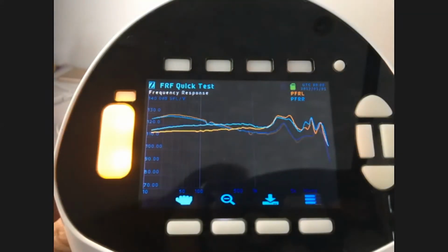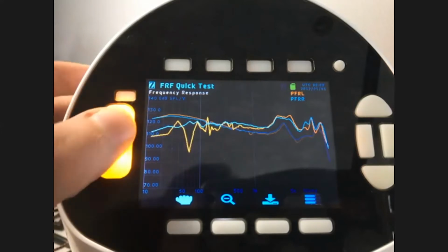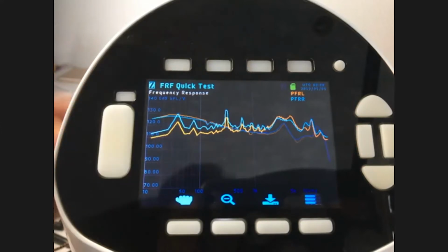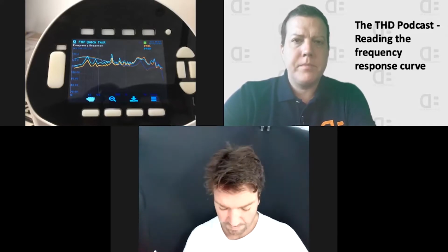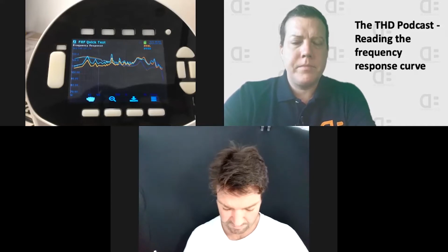So as a developer, somebody wanting to have good bass, because everybody, especially in consumer audio, they're always wanting more bass, more bass. So it has a lot to do with the mechanical seal of the earbud to achieve that goal. Yeah, absolutely. So for these type of insert earphones, in theory, if you have an absolutely perfect seal, you would have unlimited bass.